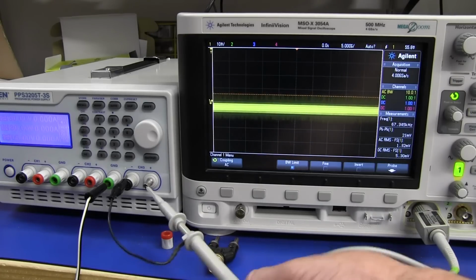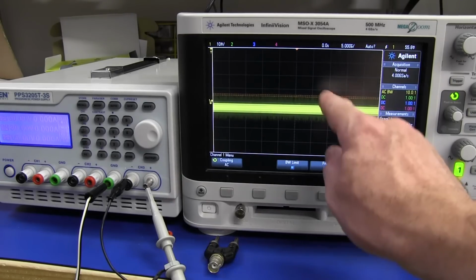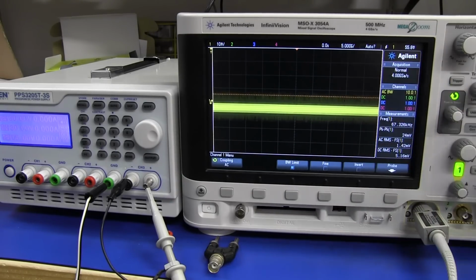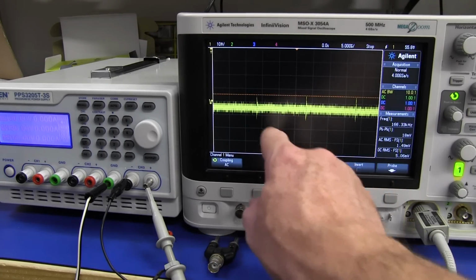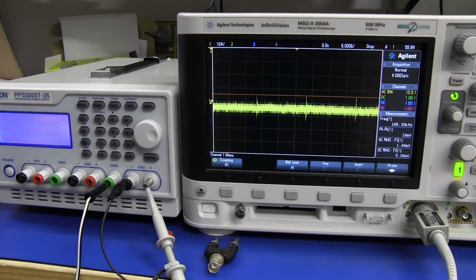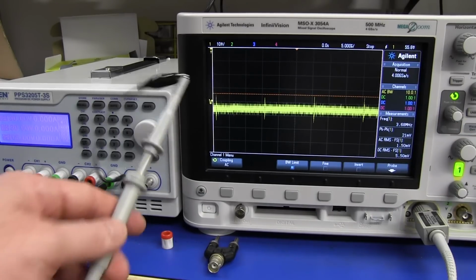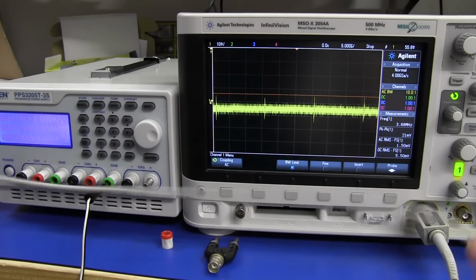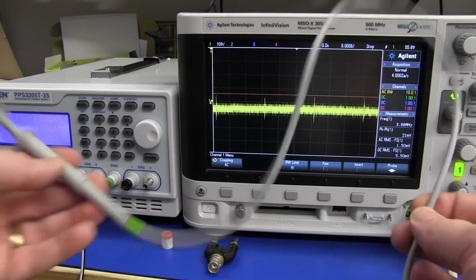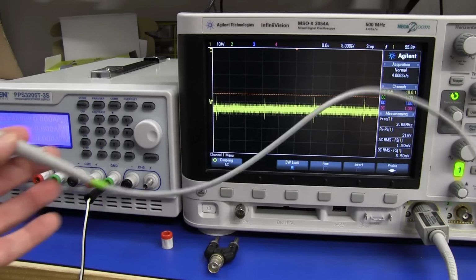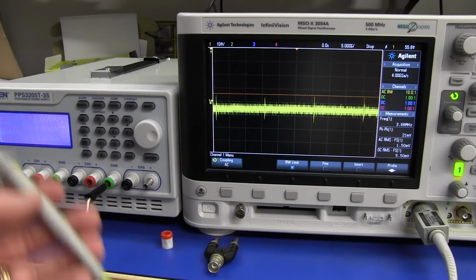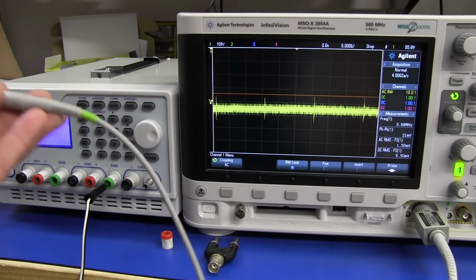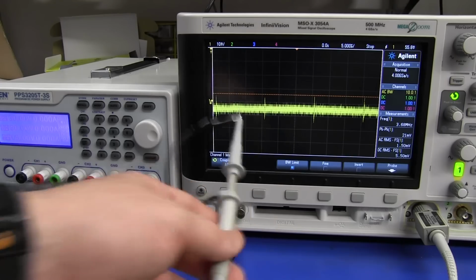Now, I'm using my scope probe to connect up to the power supply here, and look, it appears to have gone, but let's stop that. Bingo, it ain't gone. Look, it's still there. There it is, 3 divisions, 1, 2, 3. That's 66.6 kilohertz, still there. So we are getting a better result because this is a much higher quality, properly shielded oscilloscope probe, as opposed to just some regular coax, which may not have 100% coverage, but we're still picking it up.